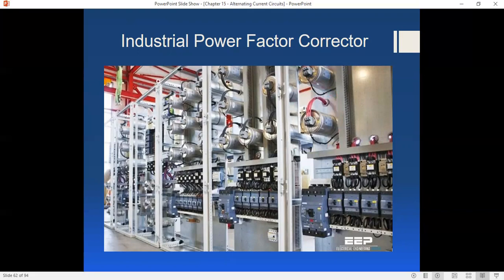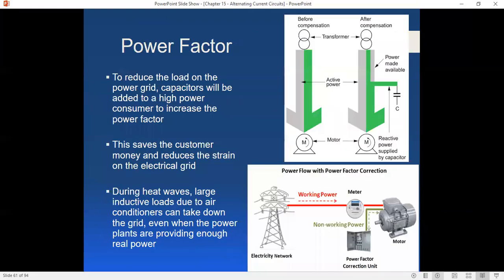When we think about what in fact is taking place here, just go back here. Ideally, you want your voltage as in phase with the current as possible. I did a terrible job drawing that. I have my peaks, valleys, peaks, valleys, peaks. There I go. You want the two to be in phase as much as possible, and that keeps the power flowing in one direction.